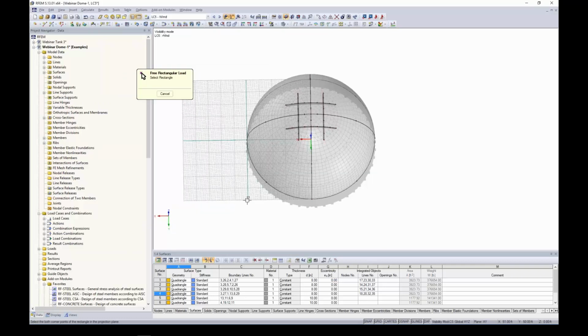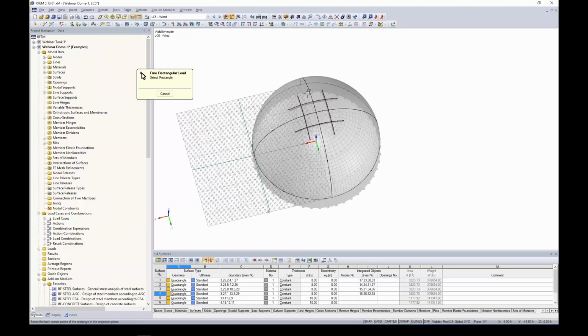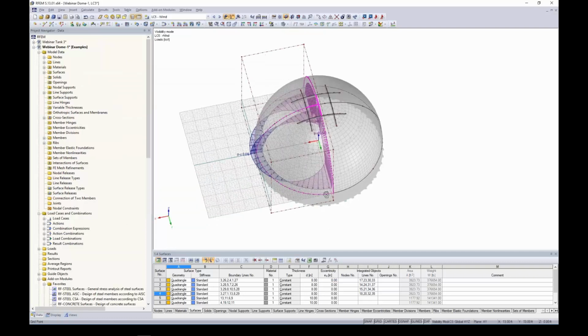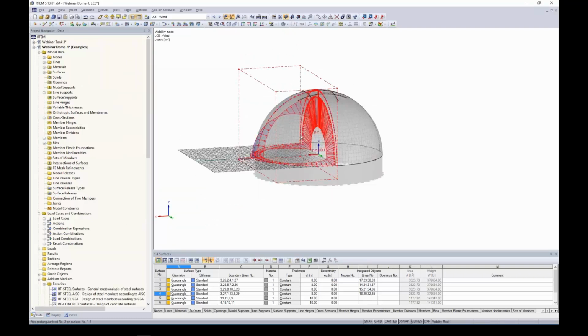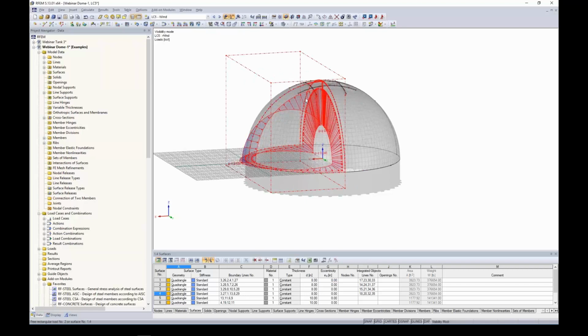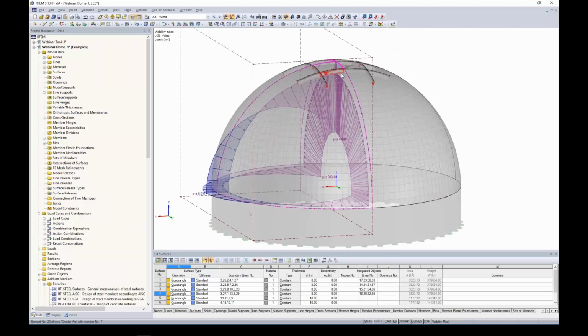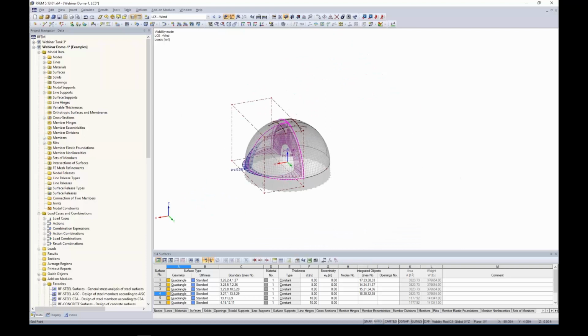This time we select a rectangular section here that encompasses those front 2 surfaces. So I actually will change this to 50 feet. We can manually change it here as well. I click OK. So now when I take a look at the pressures applied to the front 2 faces of my dome, here is my 16 PSF at the front. Here is my 41 PSF of suction up at the top, and it is displayed quite nicely.